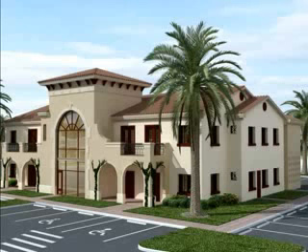However, there's a major downside to their use. They can really increase your rendering time. The more blurry your reflections get, the longer it takes to render, and this is pretty much the case with any area of VRay or Max that applies a blurry effect to your scene.